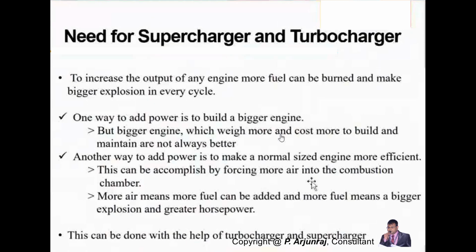Here the air which is coming from the atmosphere is being forced more into the combustion chamber. This forced induction, the air coming to the intake manifold, is being induced in such a way, by the induction principle. The supercharger will help to take the air in a forced manner. In a forceful manner, it will take it into the combustion chamber. So again, I told you, more air means more fuel can be added.